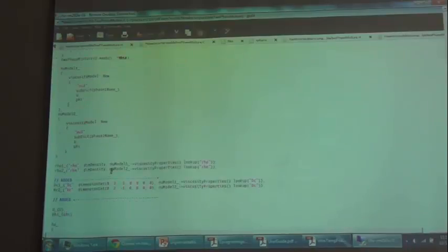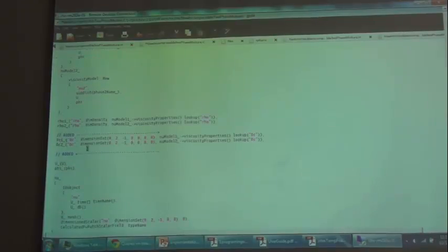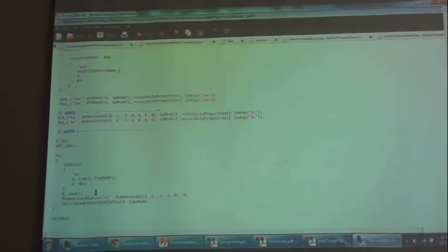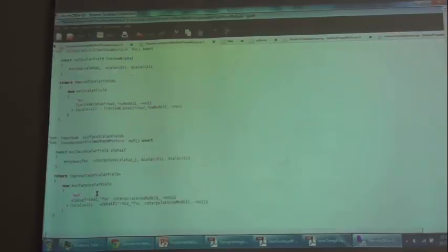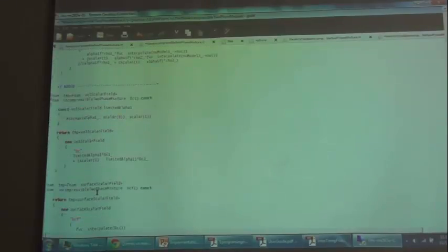Everything remains the same except for the DC field that you have to add. Again, you copy the existing template for a dimensioned scalar quantity, and you create copies, one each for DC1 and DC2, and then you create a volume scalar field for DC.